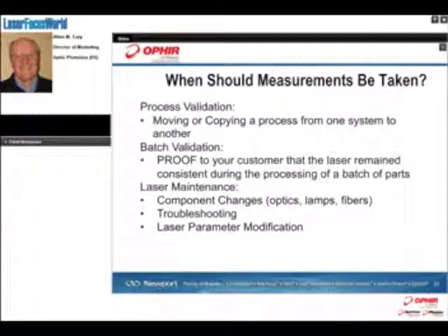And then obviously with laser maintenance, when you're doing any component changes such as optics or lamps or fibers, things like that, you need to take measurements just to make sure that before and after shots of that laser remain the same.